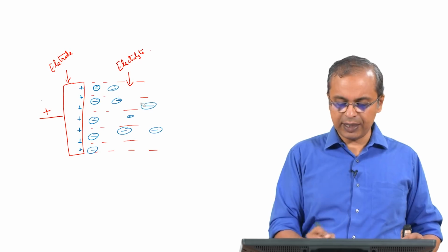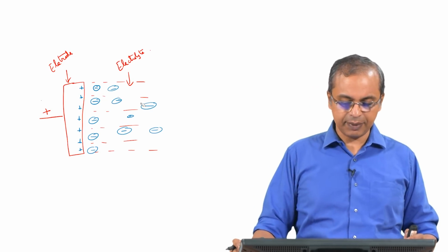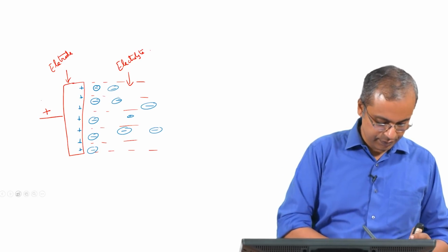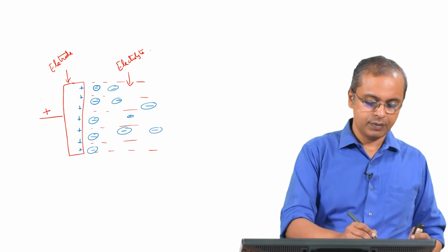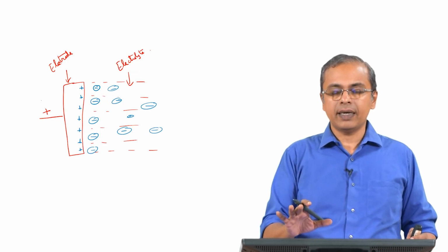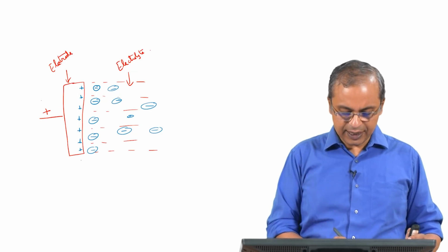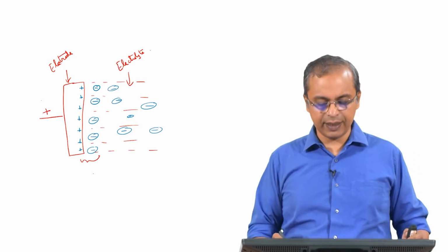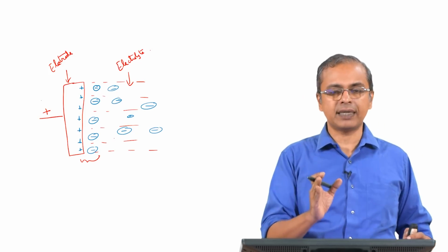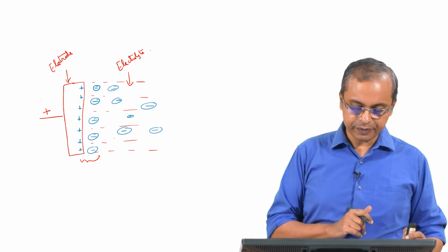So, much deeper into the electrolyte also you will have this region that is affected by the electrode. This is how the electrode electrolyte interface operates. Even here there is the notion of a double layer capacitor, but the second part of the layer is not necessarily a flat structure, it is a more distributed structure, that is the point we have to keep in mind.